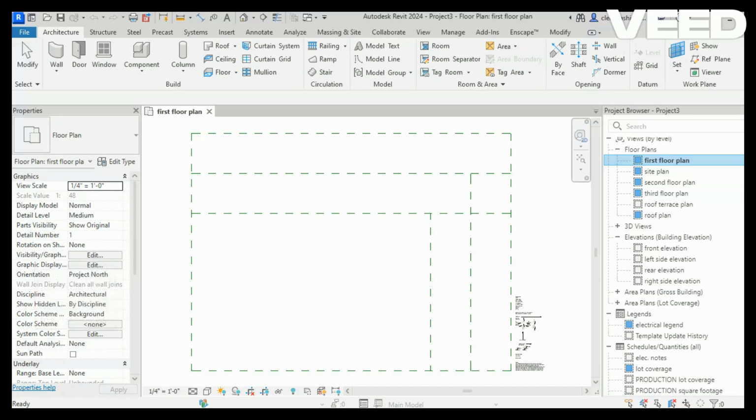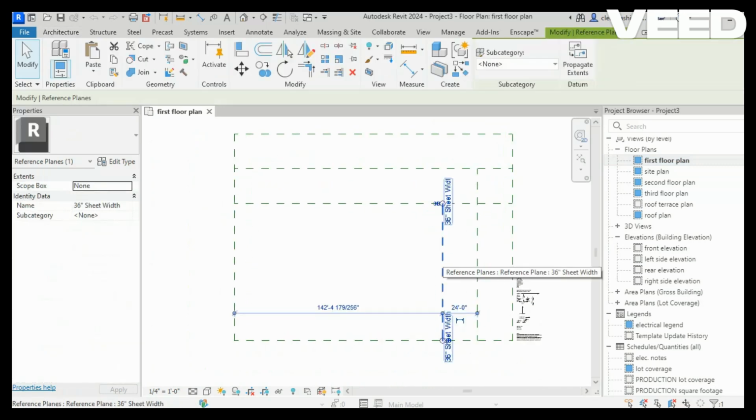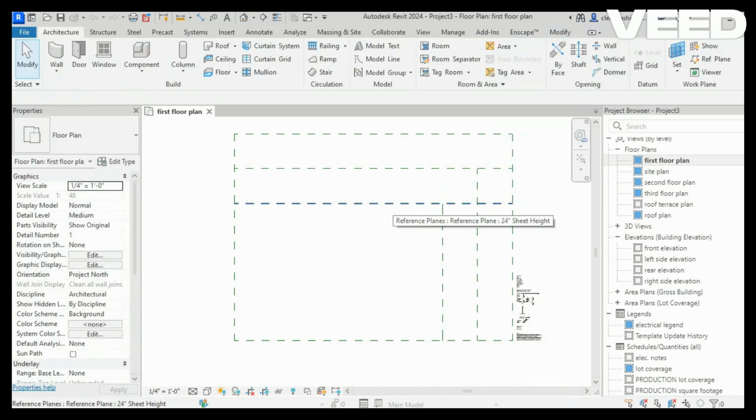So what you guys will see is when you open up this Revit architectural template, you will have a window something like this, okay? You won't have the reference planes drawn, so I'm going to hide them here. And this is something I can show you guys. It's called hiding things in view. If you are familiar with AutoCAD, it's kind of similar to toggling layers on and toggling layers off, right? So what you'll do to do this quick and dirty, because there is a portion of Revit where you can actually go in and create layers, and you can assign different layers to different attributes, but we'll get to that when we get to that.